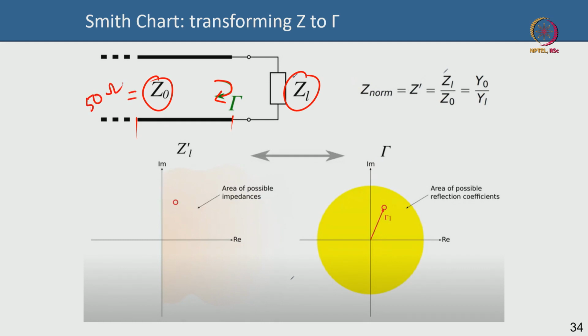That is how you build circuits. When you say I have a device that is matched, you usually mean that you have matched it to a 50 ohm line. So 50 ohm is the universally accepted characteristic impedance, and you try to make everything terminated at 50 ohm. 50 ohm is like the holy number, but in some cases it may be 75 ohm also, it is okay. So I will normalize all the impedances with 50 ohm.